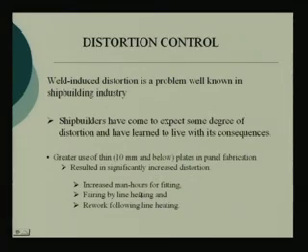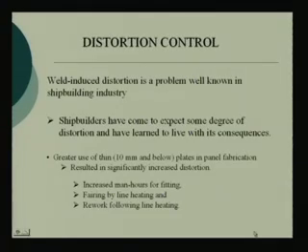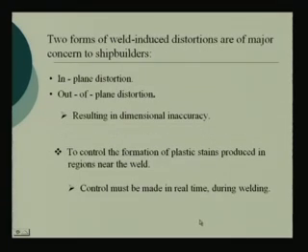So, what does that lead to? It leads to increased man hours for fitting, firstly, that alignment problem. Then fairing by line heating, you will have to fair, because the distortion is so much that it becomes difficult to align other things, put the equipment or whatever. Then again rework following line heating.